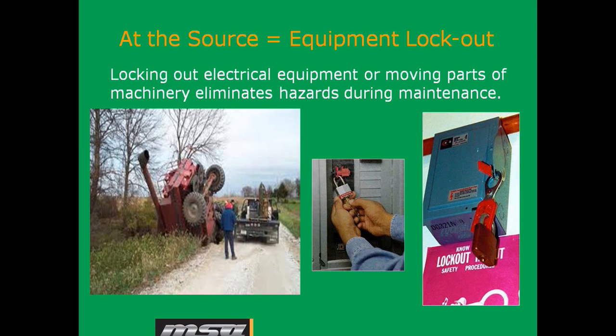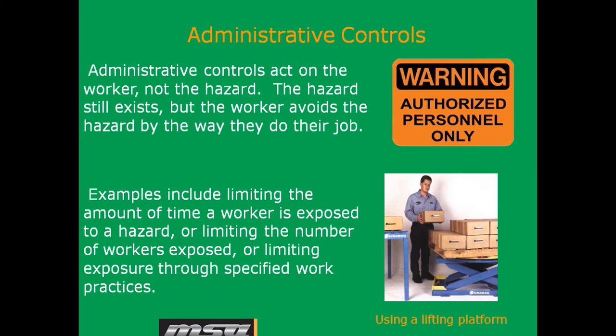So we have to take a close look at controlling this right at the source and implementing a lockout tagout procedure. For example, maybe we need to have some signage on the cab of that combine, or a sign on the steering wheel, something like that that we could look at as far as equipment lockout tagout to prevent that from happening. So this is quite a critical area that sometimes gets overlooked. But when we are controlling various steps in our job hazard analysis, this is something that we could definitely take a very close look at and see how we can address it. And lockout tagout is a process that works quite well.